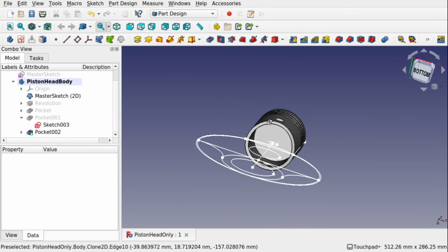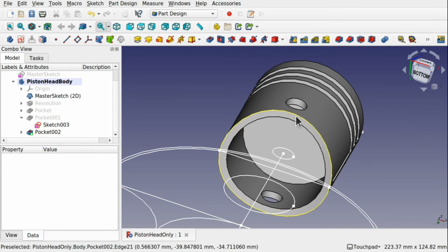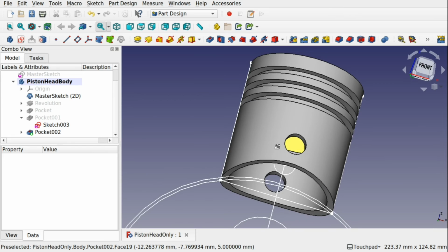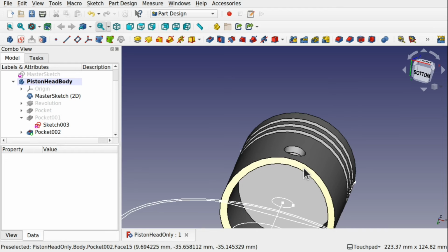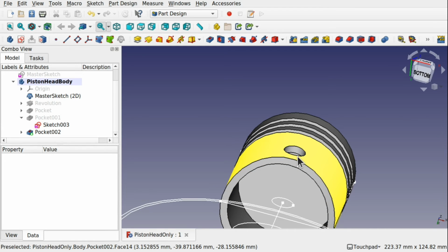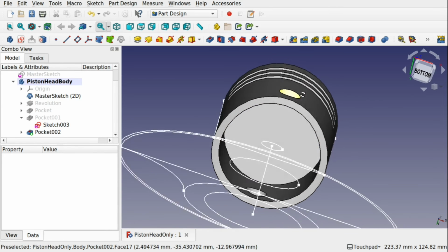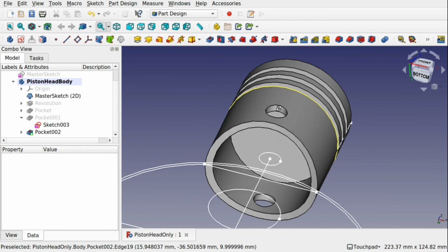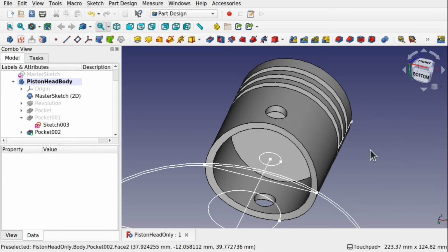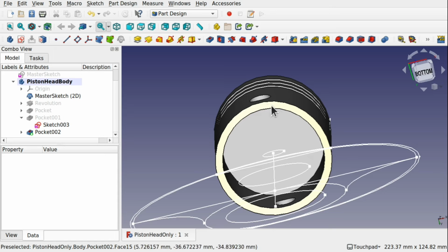There's also another point in one of the videos where I come in and take this edge, place a datum plane upon it, so I can take a little sliver across here to make this whole coplanar or planar, because we have an issue with assembly. If you look at this hole here, you can see it's got curvature to it, so it curves around. Now in assemblies you have to have planar to planar surfaces if you're doing circle to circle constraints, otherwise that constraint won't be available to you. Again, I created a datum plane along here.